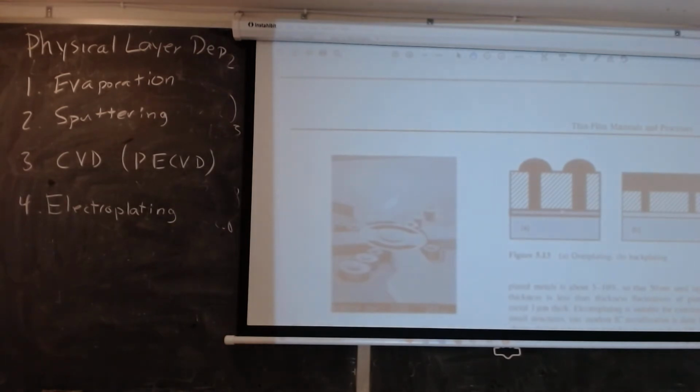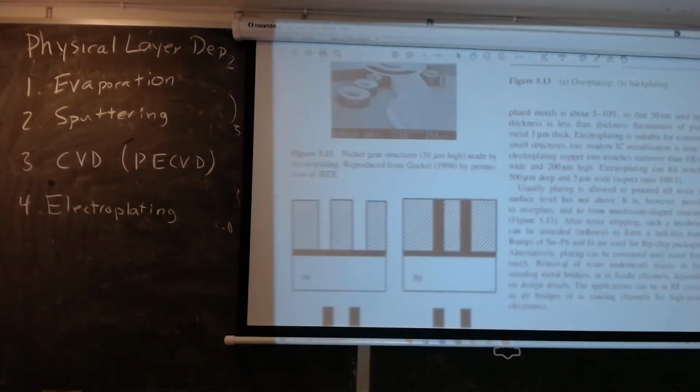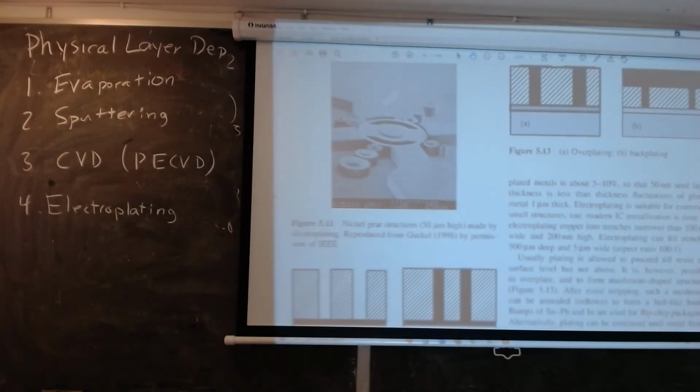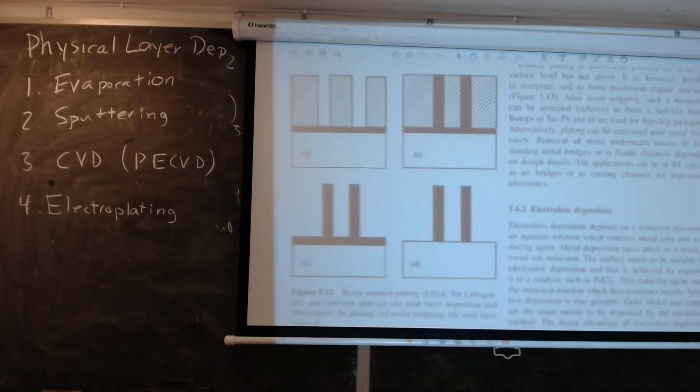See, what happens is that you tend to get overplating above the photoresist, and so you can't perform the liftoff process as easily. Now, one thing you can do, and that's this picture here, is combine electroplating where this is photoresist: you first produce a blanket layer, then deposit metal structures in the photoresist opening, use a back polishing, and then strip the resist.